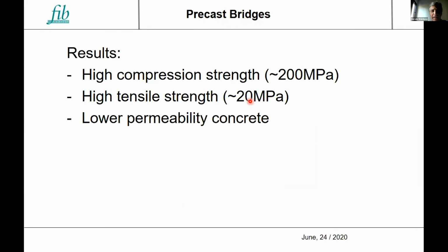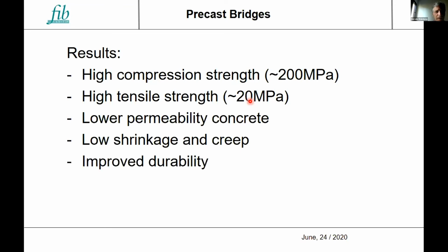Very low permeability concrete due to the use of very low water cement ratio and the addition of microsilica, thus leading to a very low shrinkage and creep material, and improving durability, extending the service life of the structure by a large amount.